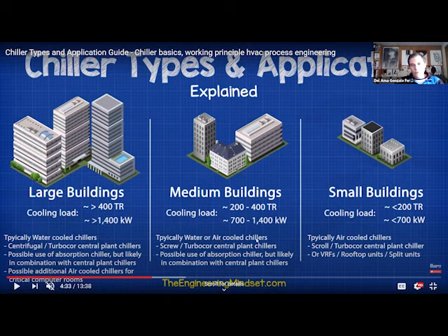So we have air-cooled chillers. Why? Because it's considered a medium building. It's not a large building. But it's not a residential building, so we don't have split units. Well, we do have split units, okay? We have air-cooled chillers with air handling units, and then we have split units. We will explain the TDS Center in the lesson because I think it's worth explaining.